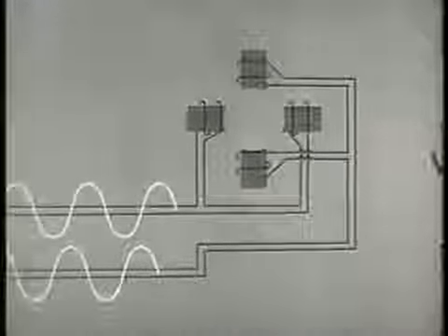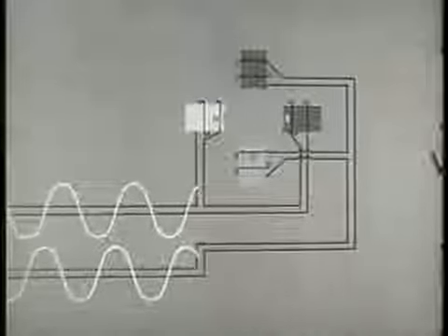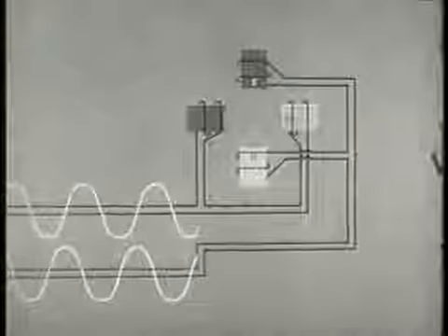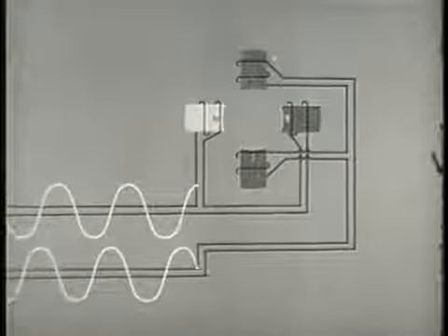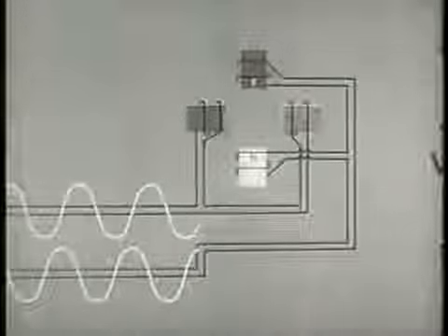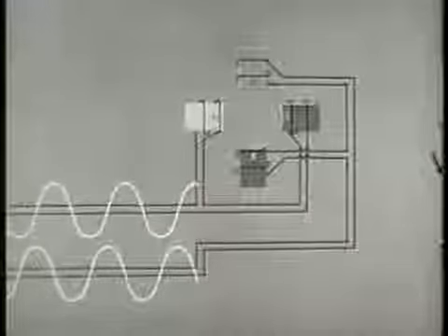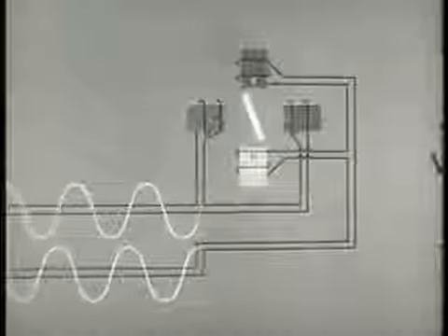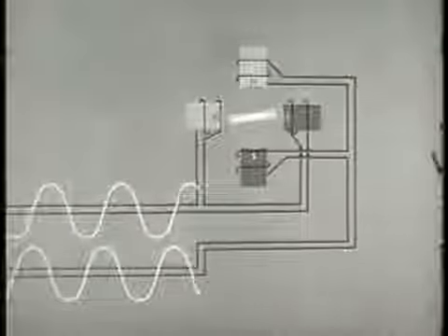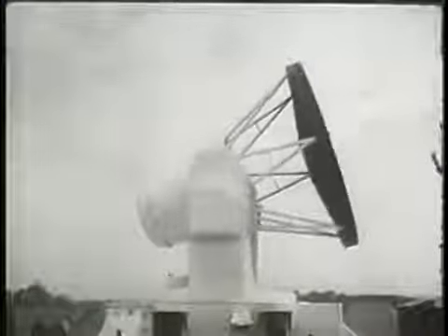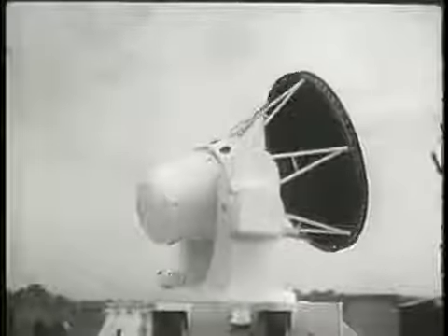Just as in three-phase motors, the phase difference is used here to energize the field poles progressively, thus causing electrical rotation of the magnetic field. As in all induction motors, electrical rotation of the magnetic field is a primary objective. Again, the rotor turns in the same direction as the magnetic field, but at a slightly slower speed. The two-phase motor in this installation is called on to change its direction rapidly.